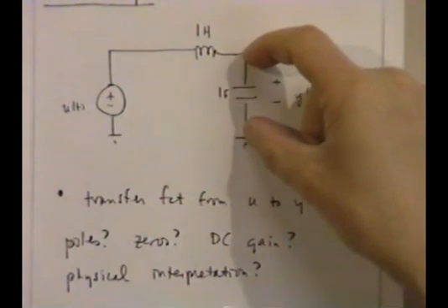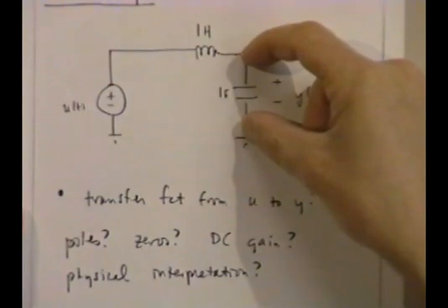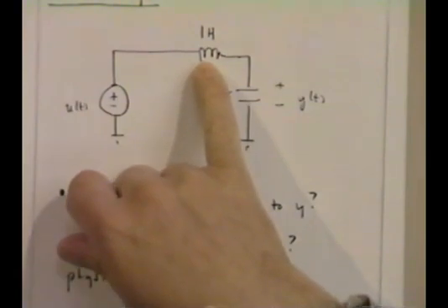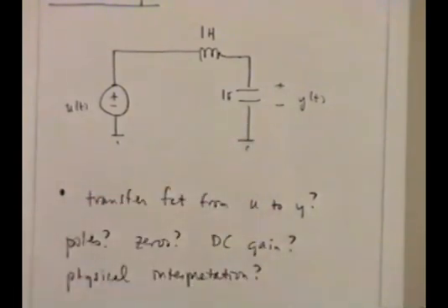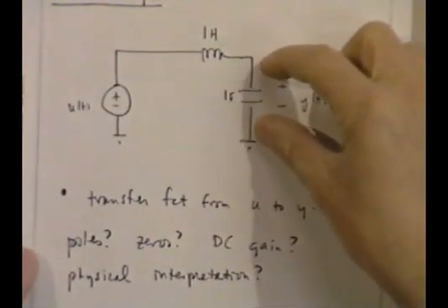And in fact, a real careful analysis would say that this signal here is not small. It's actually very small, and I mean that in the precisely formal sense. It means small squared. And the reason this signal should be small squared at high frequencies is two things are contributing to making this thing small. Number one, the inductor is going up in impedance and blocking the current flow through it. Number two, the capacitance is getting smaller and smaller in impedance, right? So, again, this is all complete hand waving, right? But the idea is basically there's two factors contributing to making this output small at very high frequencies.